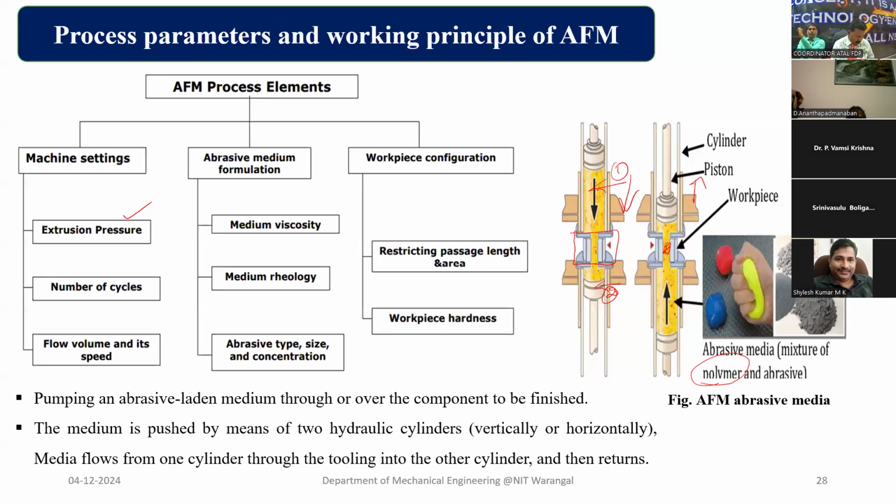So here the settings are the extrusion pressure, that means what pressure you are applying here, and the number of cycles, that is how many times you are moving the media, and then the flow volume and its speed. So how much media you are sending, and its volume. Again, how many particles the media contains, what is the viscosity of this media, etc. So that is the viscosity or rheology of the medium, and the abrasive type, size, and concentration of the abrasive particles. So these are the settings we can do in the abrasive medium.